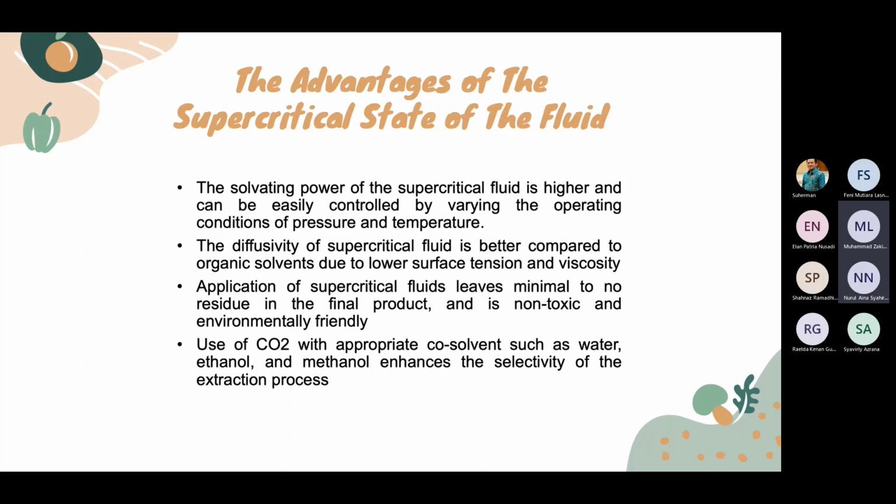Here are some advantages of the supercritical state of the fluid. The first one is the solvating power of the supercritical fluid is higher and can be easily controlled by varying the operating conditions of pressure and temperature. Another one is the diffusivity of supercritical fluid is better compared to organic solvents due to lower surface tension and viscosity. Another advantage is application of supercritical fluids leaves minimal to no residue in the final product, and it is non-toxic and environmentally friendly.